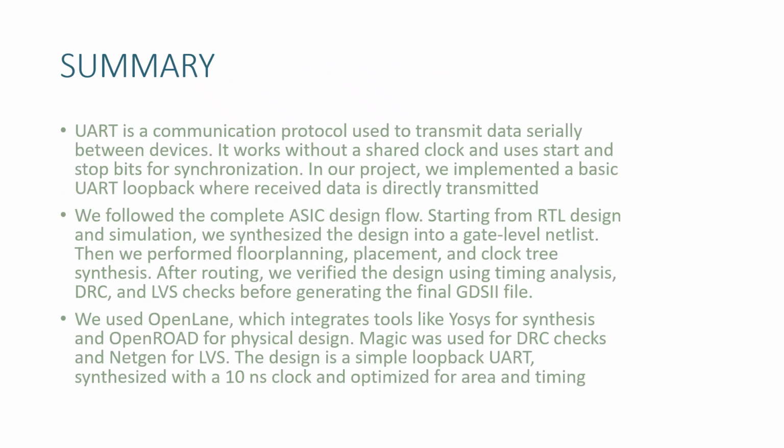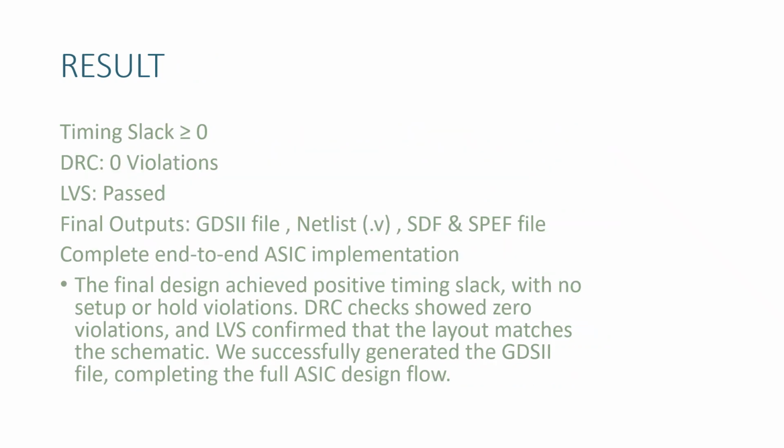In this, we implemented a UART loopback design where received data is directly transmitted, and the design flow included RTL design, synthesis, floor planning, placement, clock tree synthesis, routing, and verification. The design was optimized for a 10 nanosecond clock, and the result shows positive timing slack, zero DRC violations, and successful LVS verification. So we generated the final GDS file, completing the full ASIC design flow successfully.